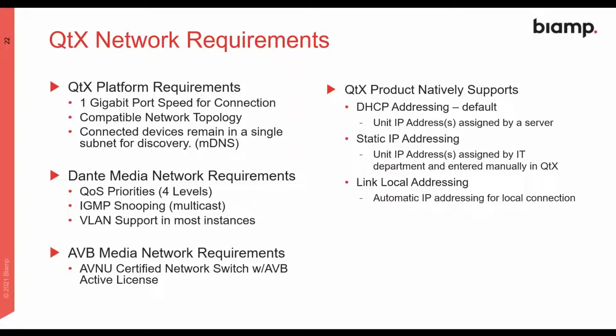What you'd run into if you did plug in an AVB system and try to share a resource, whether it be a microphone, across a non-AVB capable switch, you would get masking, because the masking is supported and is running off each controller, but you wouldn't get a shared resource. So a microphone coming in at IDF1 might not make its way to IDF4 and you'd get an AVB fault.